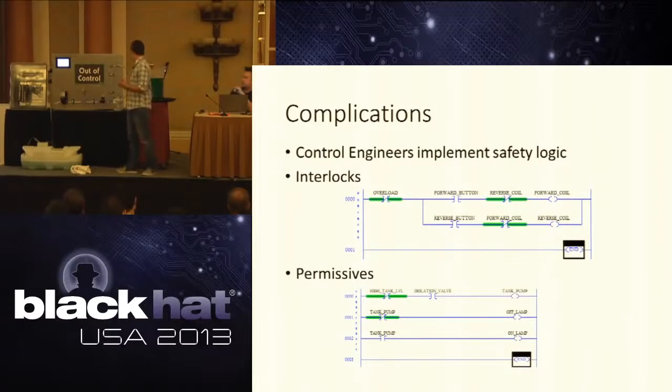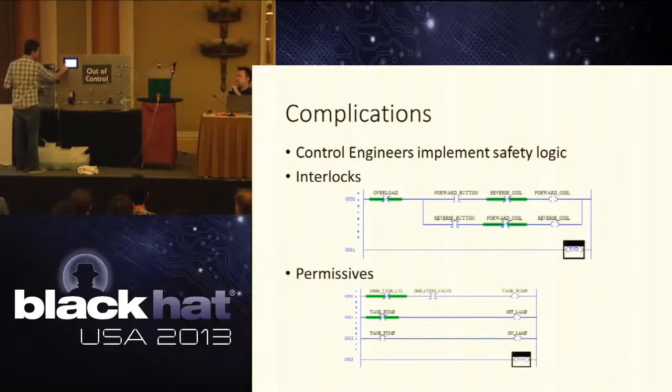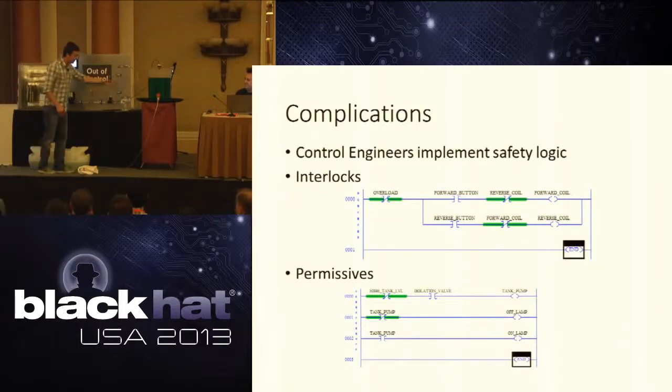Do you want to demonstrate the safety interlock there, where you try to close the valve while the pump is running? Sure. So we have our pump on, our valve is open, so everything's good, just like we showed before. And when we turn it off, our pump turns off. And we'll also show you here, while this thing's running, it will keep on pumping up until we hit 100. Sorry, you might get sprayed a little bit.